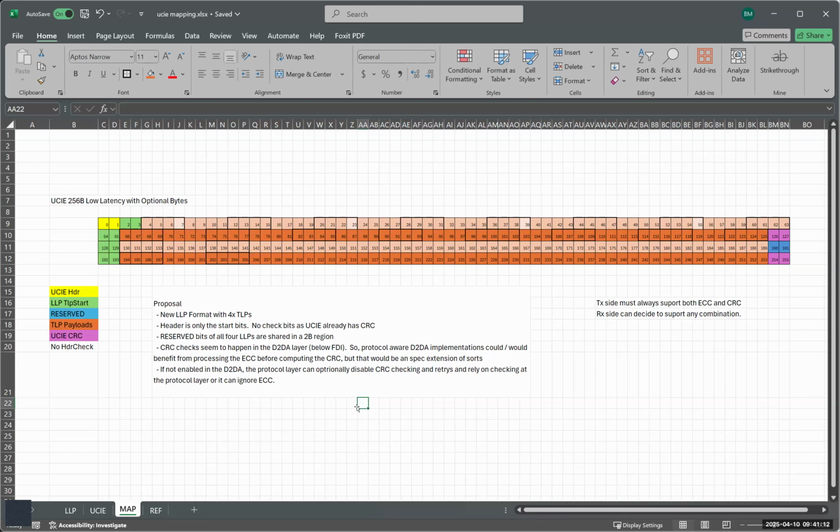And the thing is, you're not really breaking the UCIe standard, because this is still on top of UCIe. It's just adding more awareness of what the payload is in the die-to-die adapter layer, right? So you wouldn't be able to do this by default, but if you're doing an extension that enables or disables this, I don't see a problem being UCIe compatible with such a thing. I definitely don't see us requiring it.